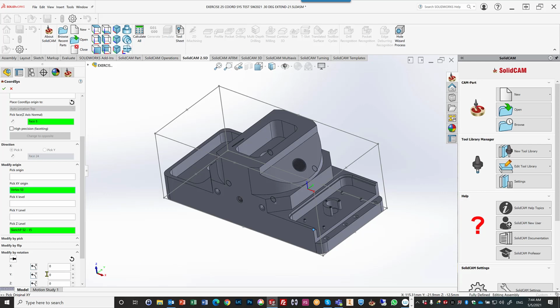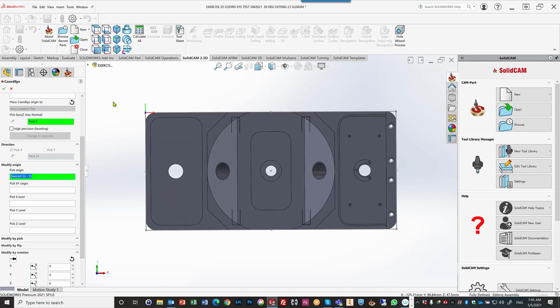Okay. Pick Z level. That's something we didn't have before. I can actually pick a Z level. I want my Z level to be there. My Z level is now there on that level itself. Okay? I want to pick my origin back over here, and my origin will go back to over there. That's as far as these fields go. Everything here, like I said, is associative. Now let's go back to my top view.